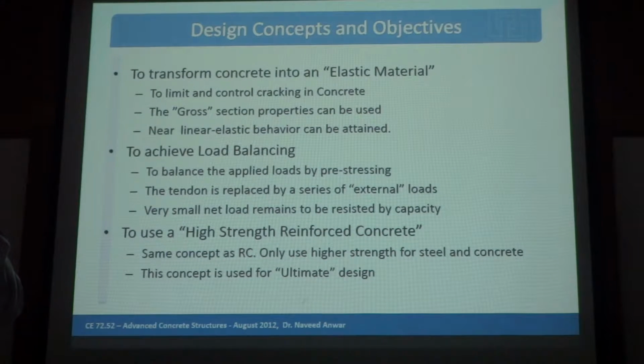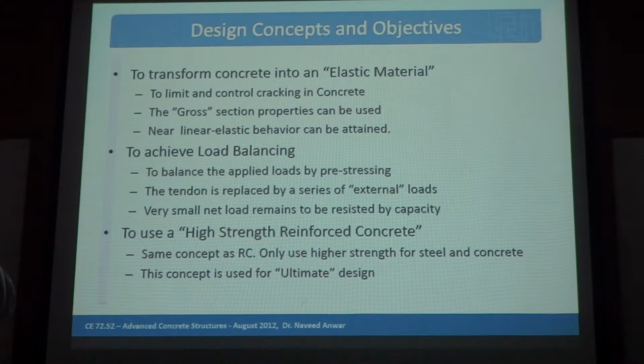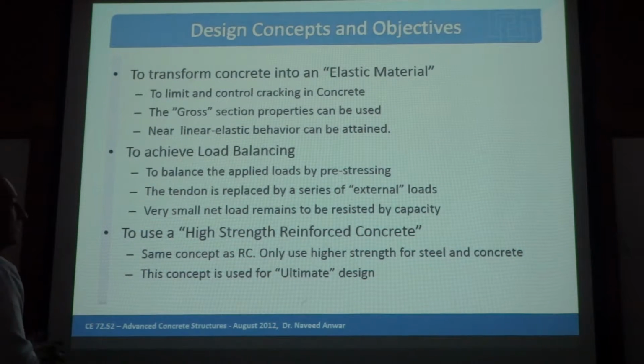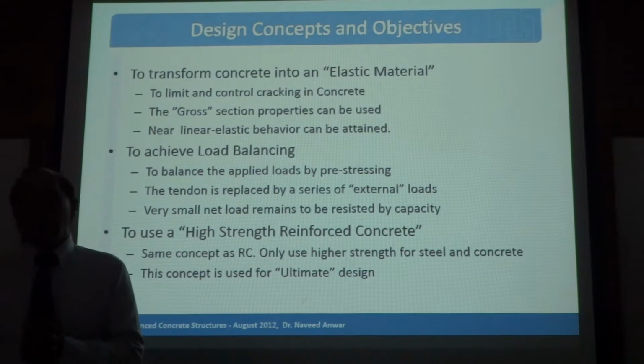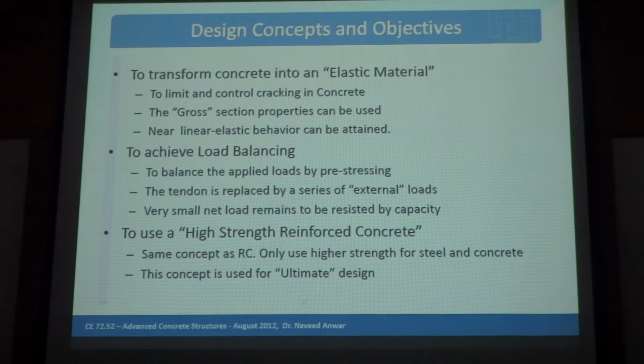So the bending moment capacity will be 5 times more, and that comes free to you, because actually you put it for pre-stressing, but the pre-stressing is no longer available for any reason, or exceeded already. This bar now becomes available to you as a high strength reinforcement. So it's a free ultimate capacity that you achieve from the same process. So you get these 3 very interesting advantages by using the pre-stress. Is everybody clear about this? Good.